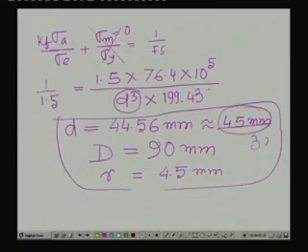Oh, well, as I was telling, you can have a small iteration by again considering this 45 mm in the size factor and again recalculating the dimensions. However, that change will not be to that extent, because there is a cubic function involved in it. So, this is one example by which you can find the dimensions of a machine element considering the fatigue design.